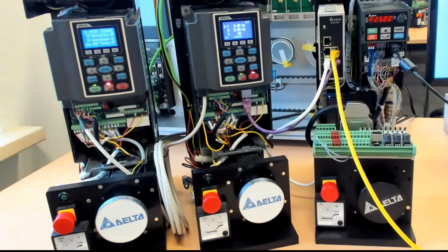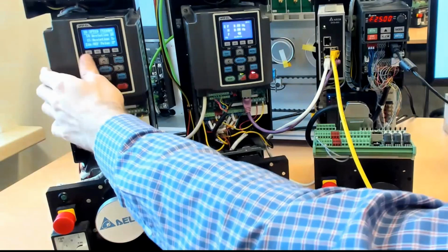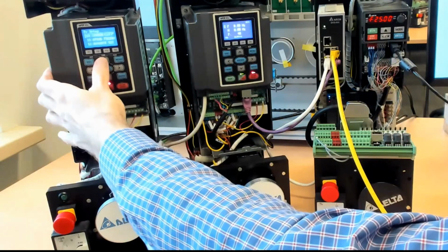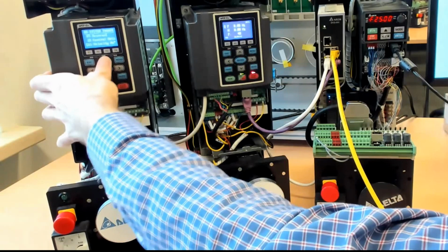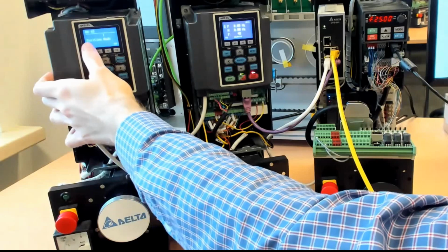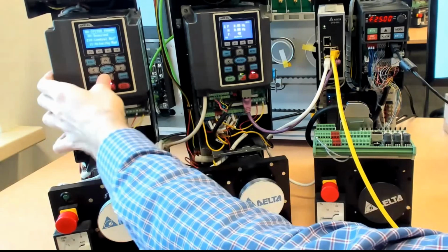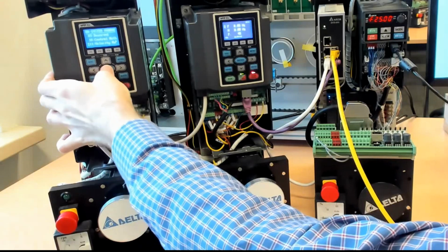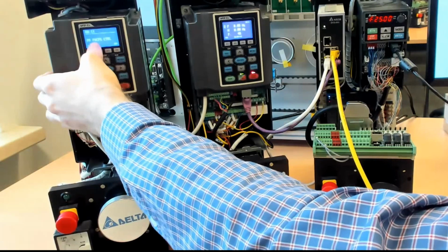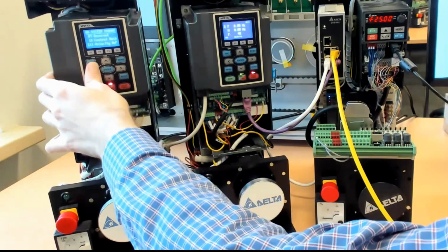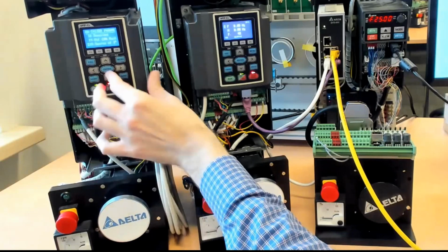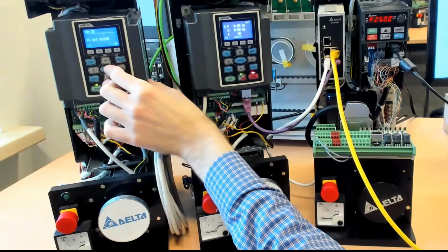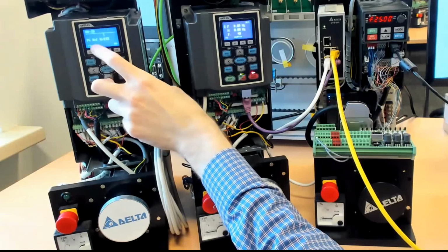Since the follower drive is running in positioning mode, you actually need to define this in parameter 00-10. You need to set it to 1, position mode. And of course, if you're running in positioning, then you also need to run in field-oriented control for PG. You need to tell the drive which should be the source for the control, so you need to set parameter 00-20 to 5, PG reference.